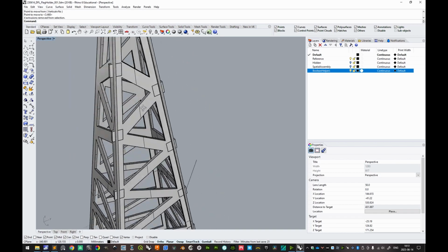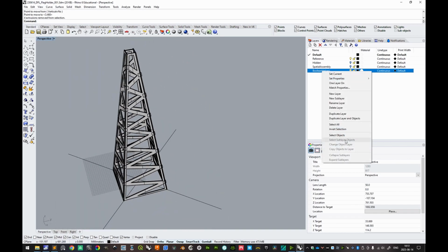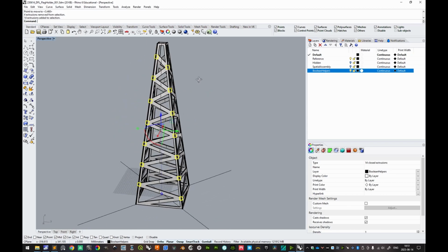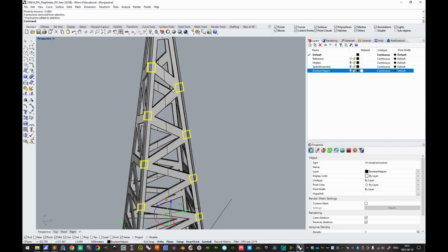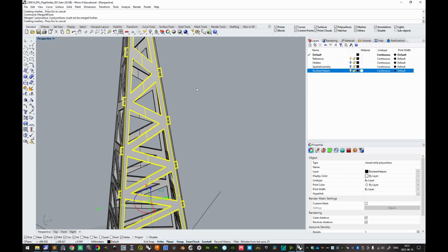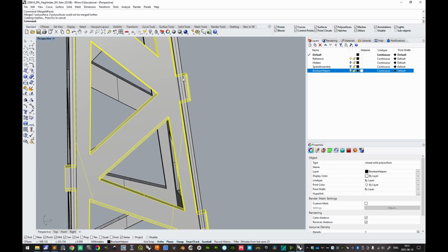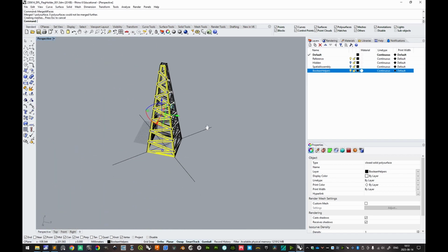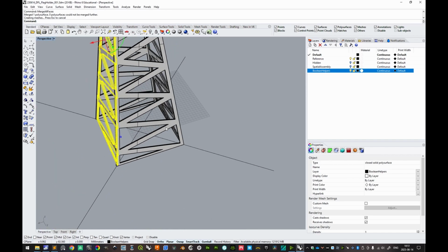Now this looks very good, and then we can select all of these Boolean helpers, and perhaps it's most beneficial to our time here if we simply Boolean union with this one, and then do merge all faces, so that all faces that are coplanar are merged into one, and then we can simply mirror this.